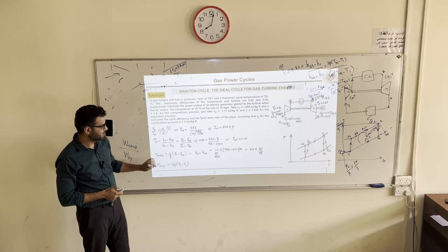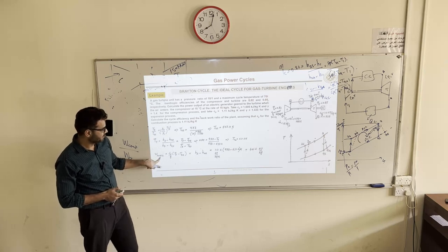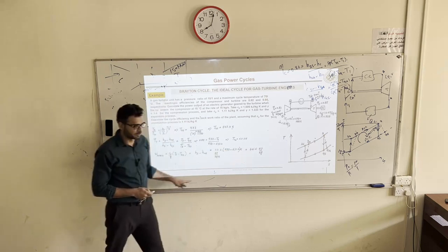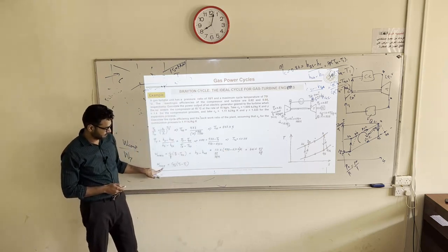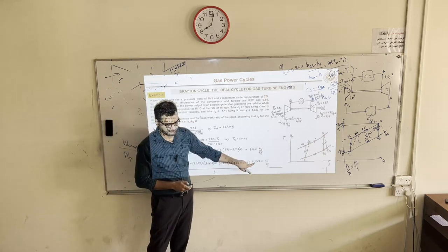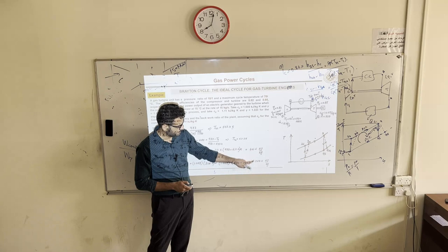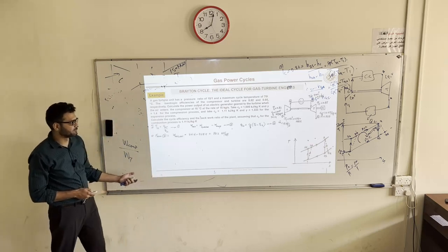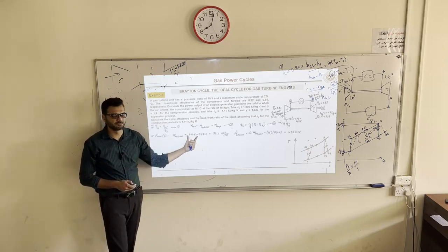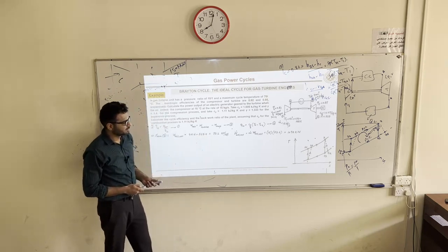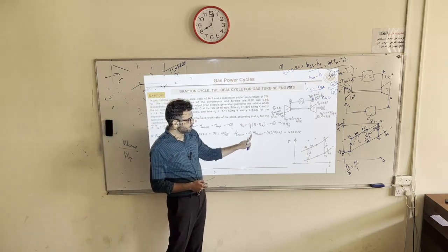Work of turbine, only work of turbine is this much per kilogram, written here, 401. And what is work of compressor? So you can see a major part is reused here. So the net work output is very small, only 73 out of those 400, only 73 is the net work output. So multiplied by m dot will give me the power.